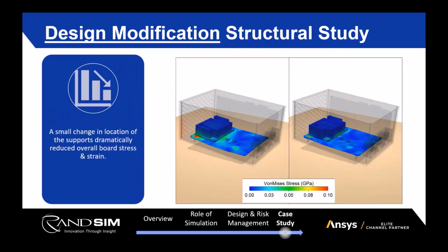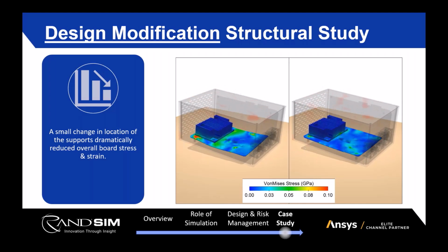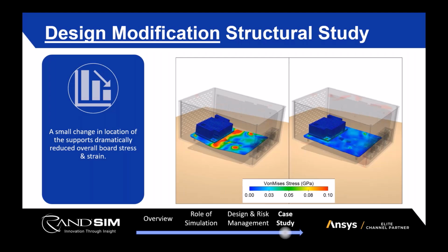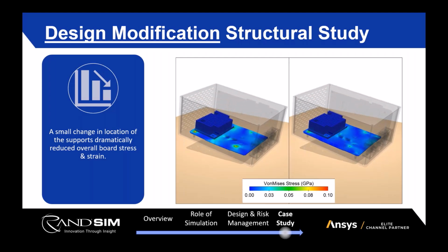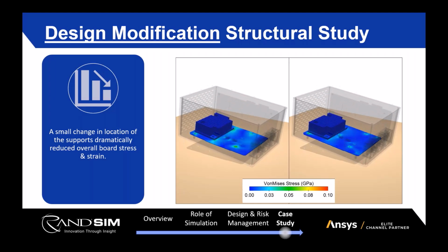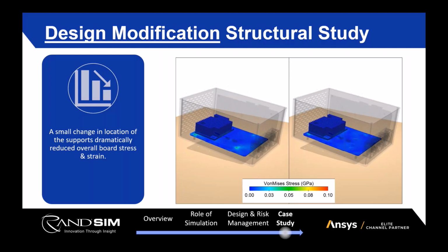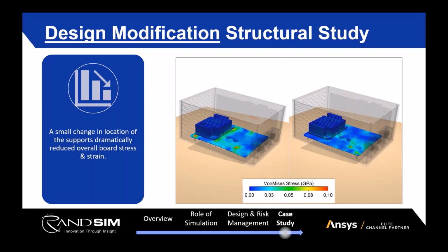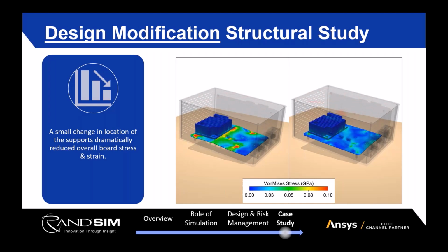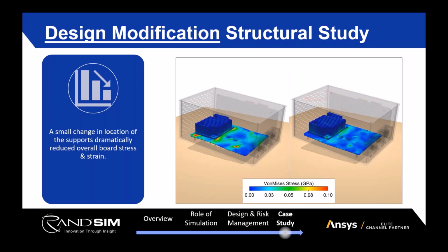And then on the structural side, I was able to go in and add in those additional supports. And this substantially increased the PCB's resilience because it wasn't going to be exposed to as high of strain. So you can see this here in the video showing that instance of the drop test right as the enclosure is meeting the ground, and how the PCB on the left side, which is the original design, had a very high stress induced right at the junction of where that heat sink met the PCB. Obviously, deflections in this video are accentuated for visual effect, but on the right side, we're seeing a substantial reduction there, only seeing some higher stresses at the areas where the PCB is junctioned down.